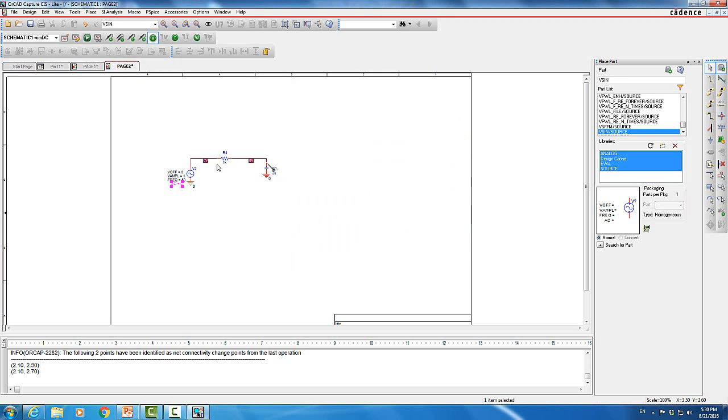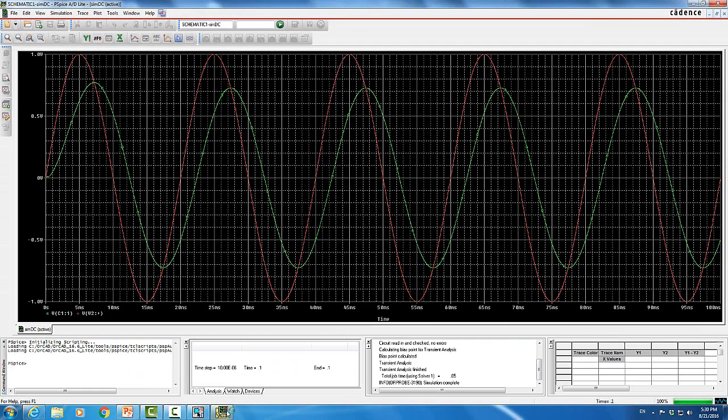So basically we defined the simulation type, which is going to be transient simulation. Now we are also going to measure VI, which is V2 here, and V out, the voltage across the capacitor. When we run the simulation, we're gonna show what VI is and what V out is. And now we're gonna run the simulation. It might take some time. It's actually fast. You can see that we have 1, 2, 3, 4, 5 cycles. They are nice sine waves because the resolution is around 10 microseconds, and that is good enough.